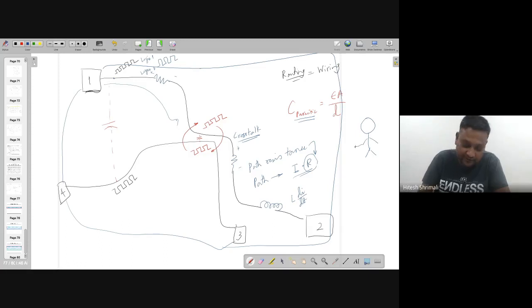You are full of charge because, say, you are in Mandi in winter season, you might be wearing some jacket or something where you are having static electrical charge, right? When you come nearby and you see such a long wire inside the IC, what will it do? It will dump these charges over here, and such a thing is known as the antenna effect.